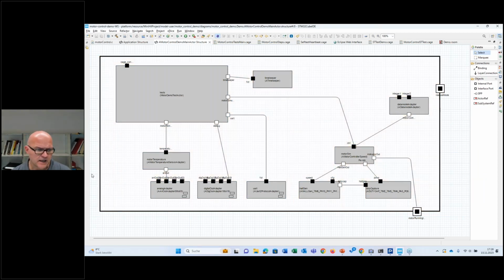So in the model, on the lowest level, you have the I/O adapters, analog, digital, for example UART, then the duty capture unit for the PWMs. They are measured, they are fed into the motor simulator. The motor simulator calculates the new speed and tells the Hall generator with which frequency the 3 digital outputs should emulate the 3 Hall signals.